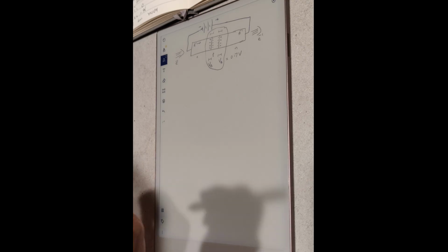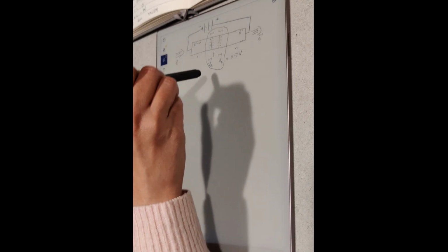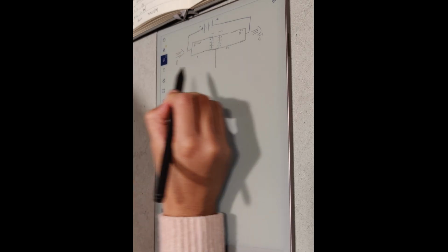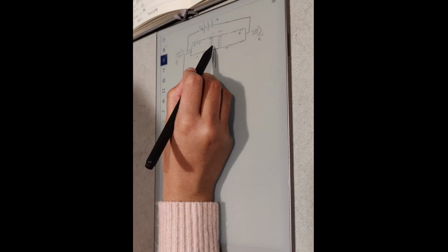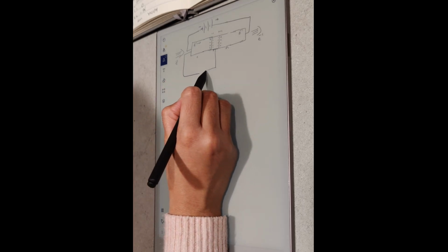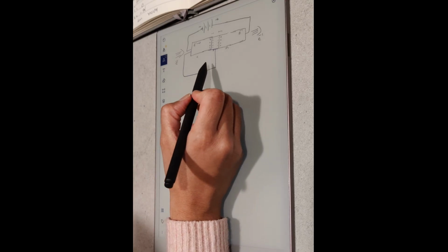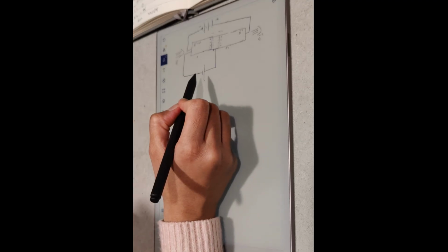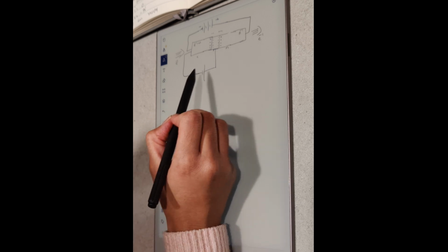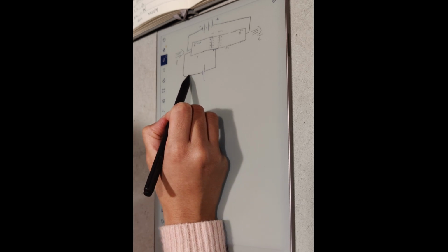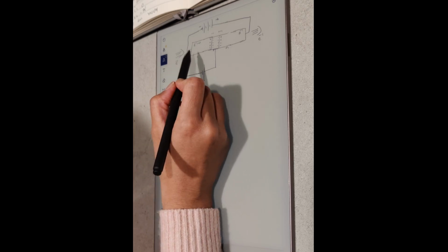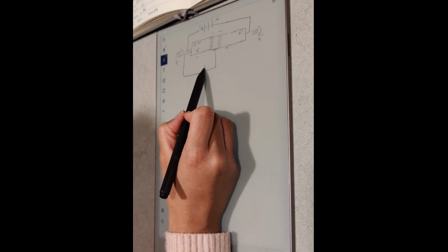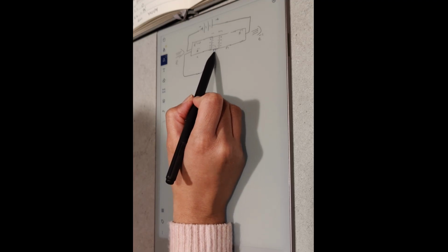So now, let's connect another battery. So I'm going to just remove this so that I have space in this way. So I connect these two, N and P, and I make them forward bias. So forward bias is where the P side is connected to the positive and the N side is connected to the negative. So this is forward bias. If I do this, now what happens? So now, again, this battery, the negative terminal is going to push the electrons this way. So electrons are going to go here. And here, because this is positive, it's going to attract the electrons.